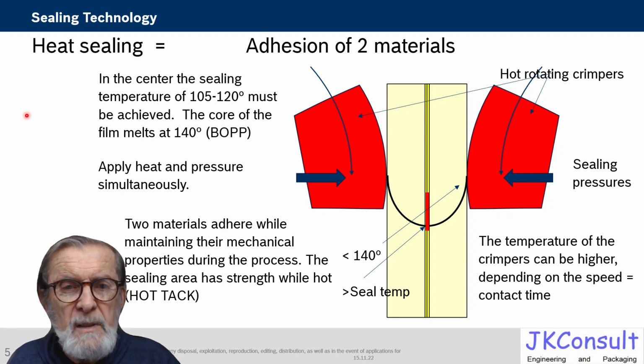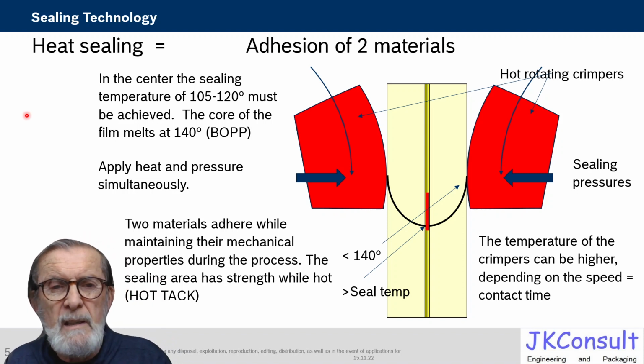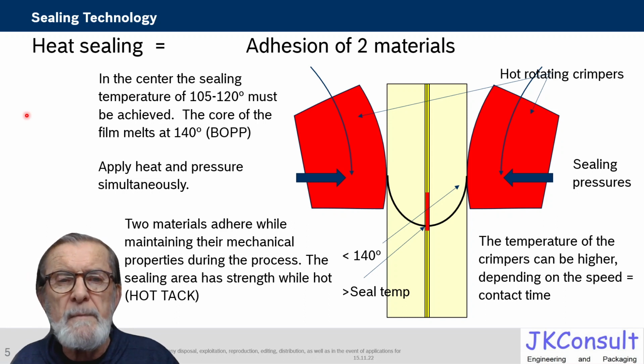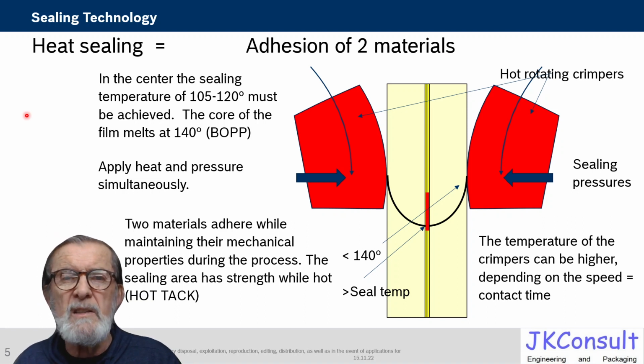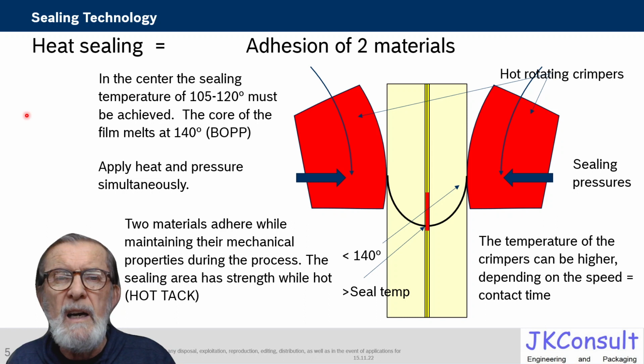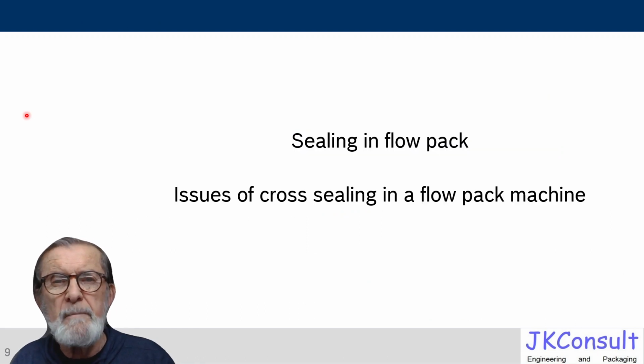Important is that during the sealing the film maintains its mechanical properties. So it is hot, and the attachment, the adhesion, is such that it has a tack at hot temperature. So hot tack will hold the seam together even if there's a load on it. That's the difference with welding.